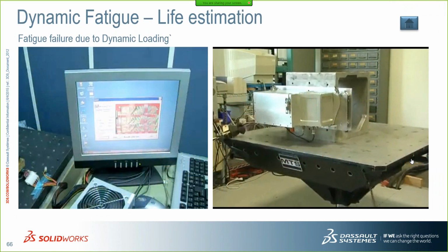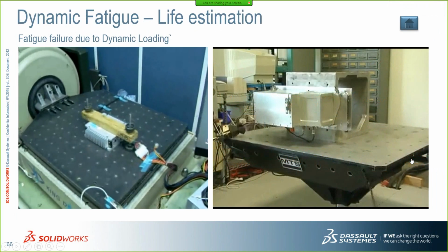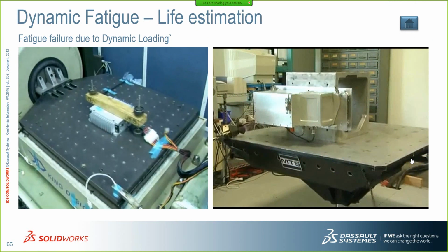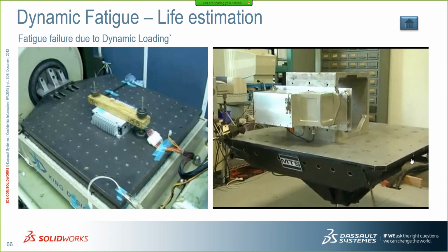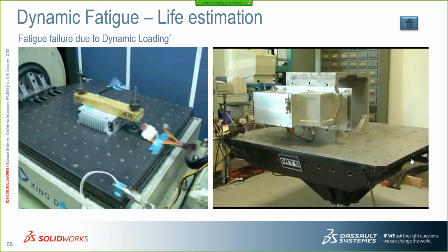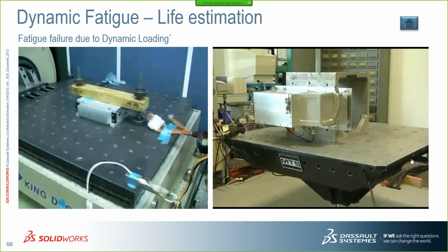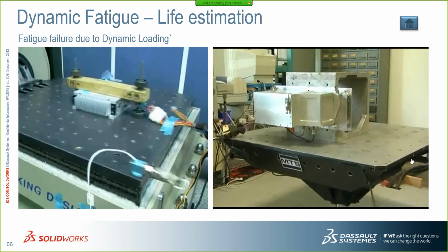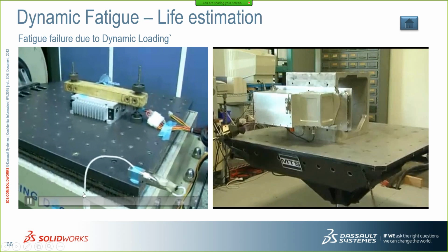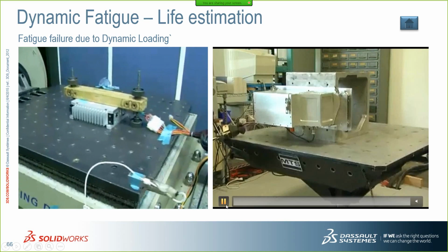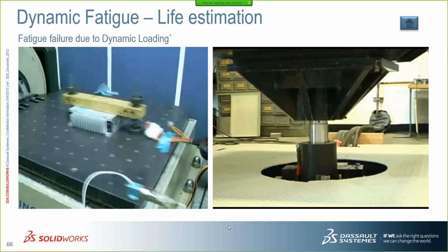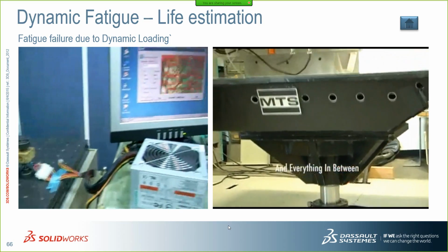Moving on, the third one could be fatigue analysis. Now we have already discussed fatigue during simulation professional. So in the software I may not go in detail, but in this particular module, as we are getting the capabilities of nonlinear and dynamic, we can as well simulate the life, or we can understand the life of a component which is subjected to dynamic loading, or it could be also random loading. The best examples of these are the ones shown here on the screen, wherein a typical shaker test analysis is happening in the lab, and this can be simulated as it is in the software to understand the life of the component.